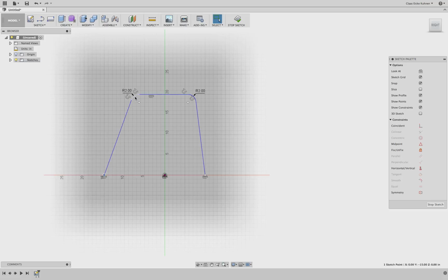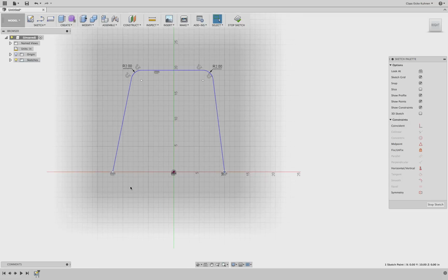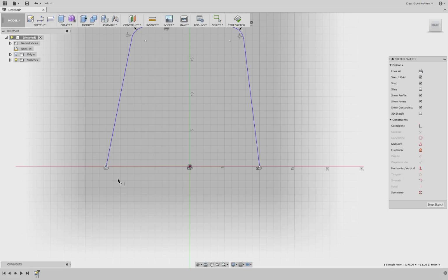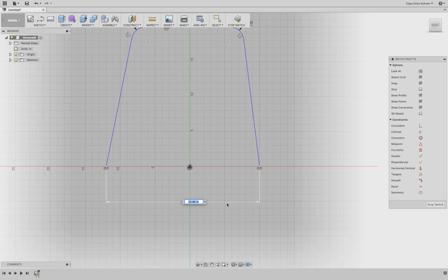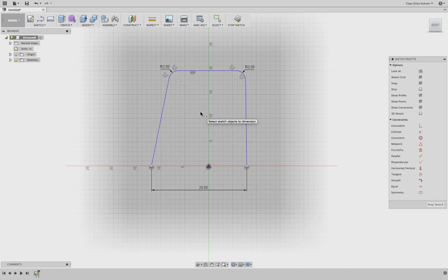And because we have the fillet constraint with a radius, you see I can adjust this leg and adjust then the rounding. Perfect. The distance between these 2 points should be around 20, so we can add a distance marker or dimension, 20, there. Okay, and can maybe move this one over and use the grid a little bit to adjust this, but that's not necessarily perfect. So